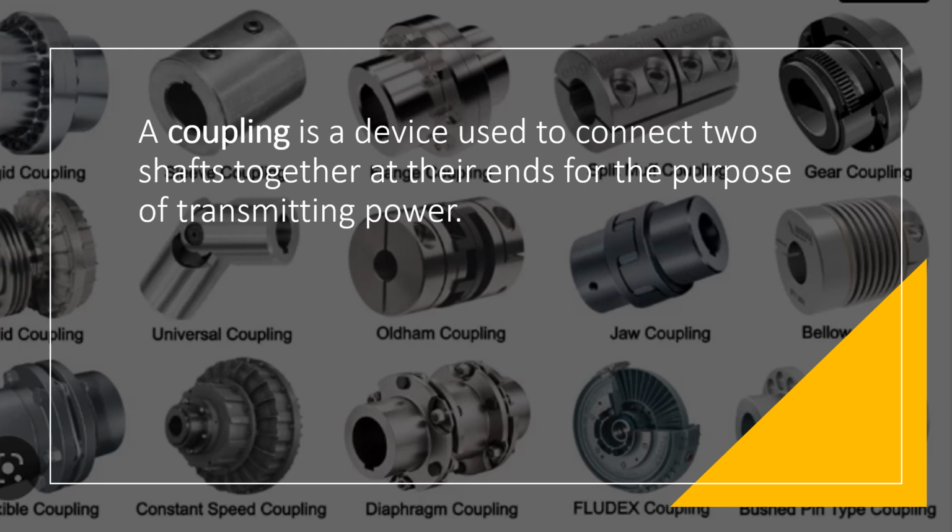If you put a driver and a driven with a coupling, then there are a lot of things that need to be checked. Those possible problems which may occur, I covered already in my past videos, which is called how to do coupling alignment. What are the possible misalignments, step by step you can learn how to install a coupling, what are the steps, how we can put the shims, what is the angular misalignment, what is the linear misalignment, which code is referred for this alignment purpose. It is part of API. If you know API 686, chapter 7, it is there.